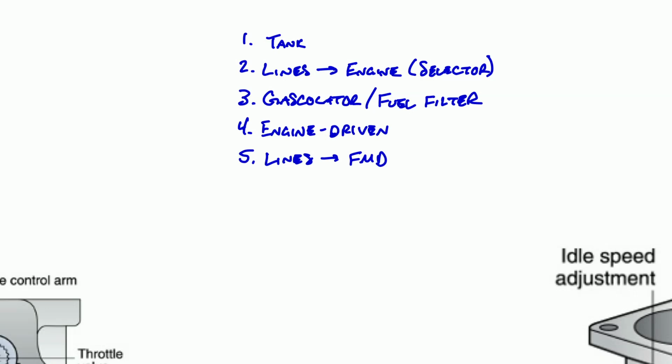We'd also want to make sure that as a part of our run-up on the engine, we observe that we're actually getting the correct fuel pressure from the pump. So if we have a fuel pressure indication gauge in the cockpit and we have control, we can switch off a boost pump while the engine is running and make sure that we maintain the correct PSI throughout the range of operation off of the engine-driven pump to make sure that our relief valve is adjusted properly.